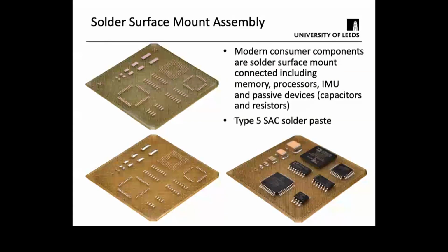Basically, what we tried to do was cover a range of different modern components, including passive devices. When you look at modern passive devices like an 0201, they're virtually down to the size of a grain of sand. So we produced our substrates, as you can see in the top left there, with a copper. Then we dispensed a solder paste. In this case, we wanted to use what the industry uses. So we used a lead-free solder paste, and we used the most predominant, the tin, silver, copper.